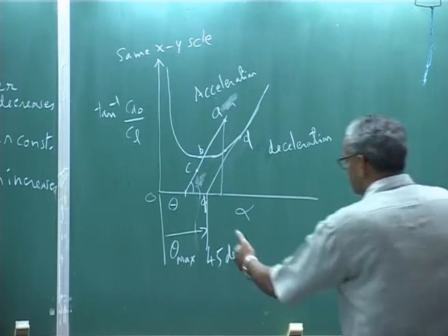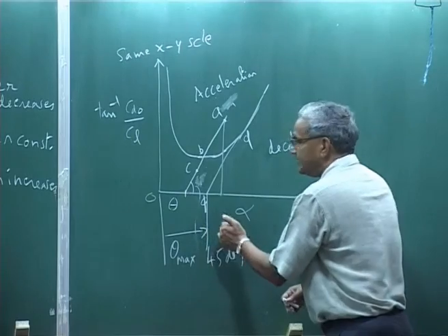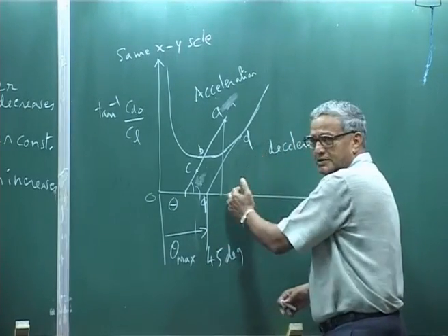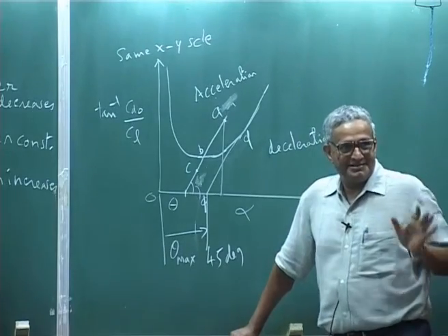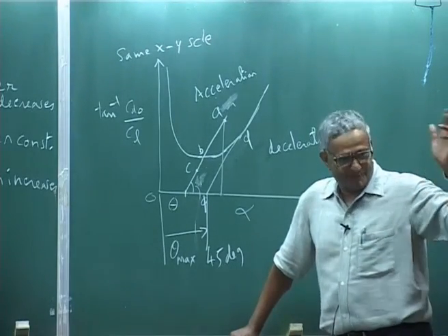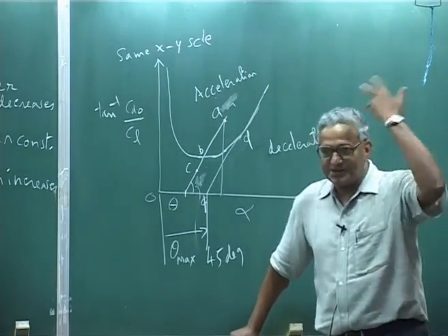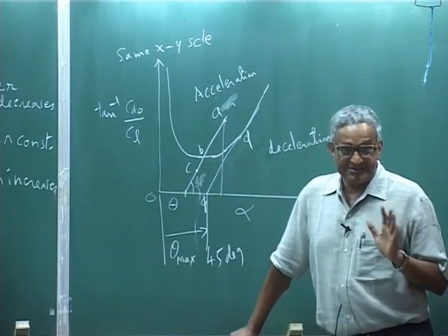Otherwise, if you go to a pitch angle beyond this, every point is deceleration. So the rotor will simply decelerate from the initial omega r, it will stop and it will start rotating in the opposite direction. That is very dangerous.